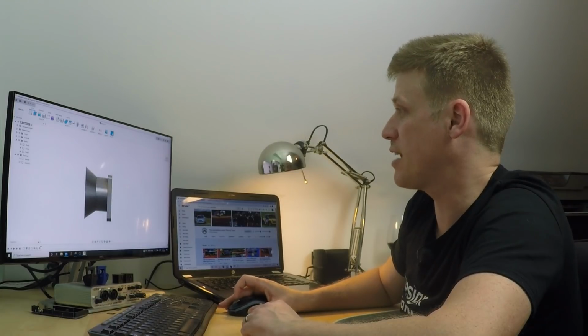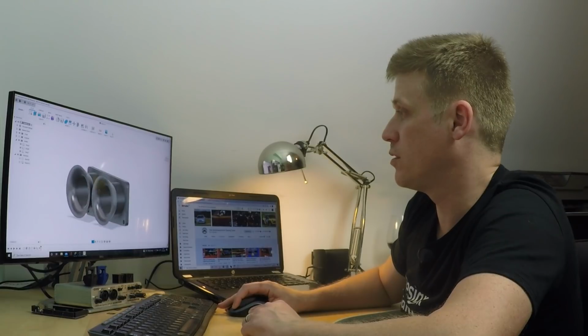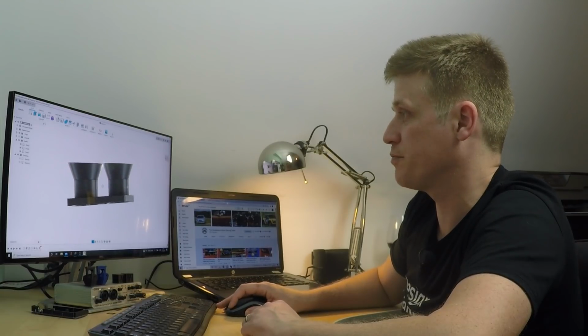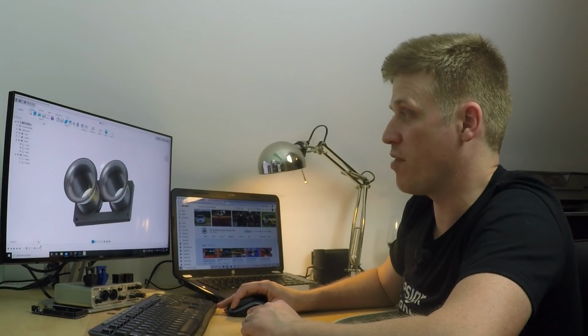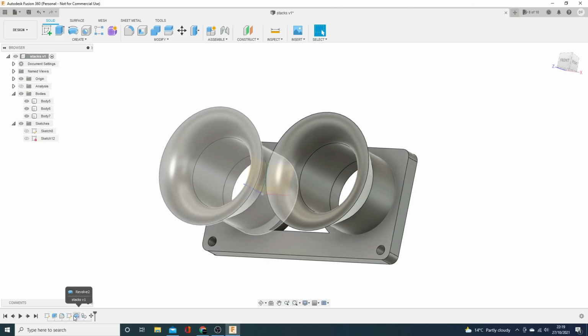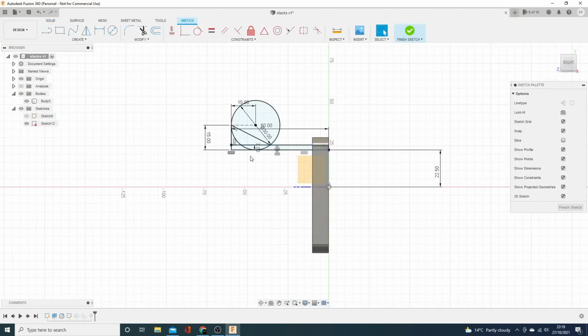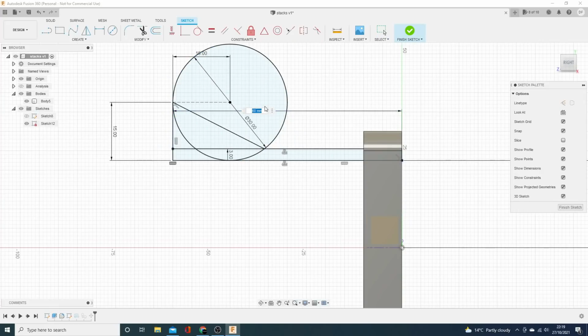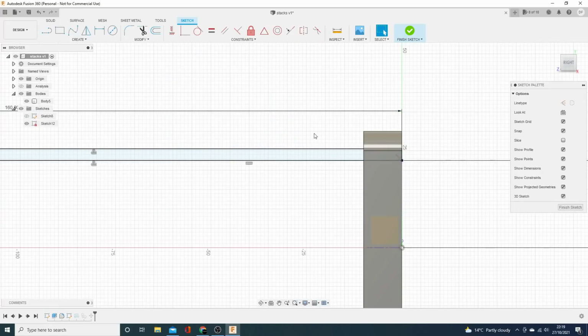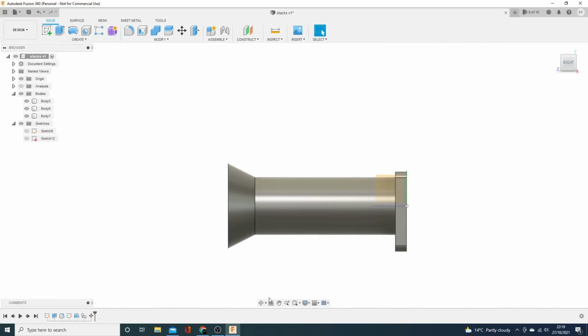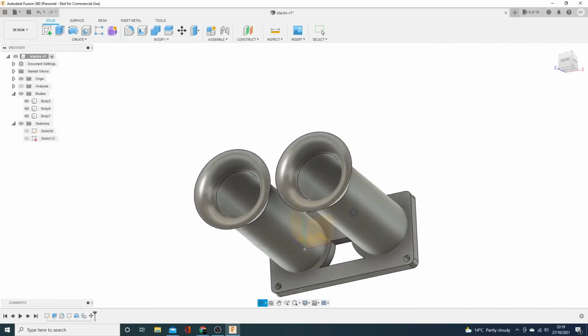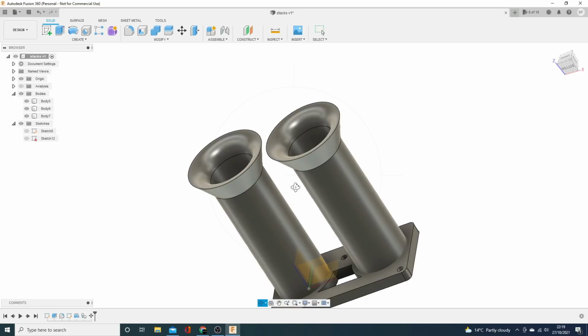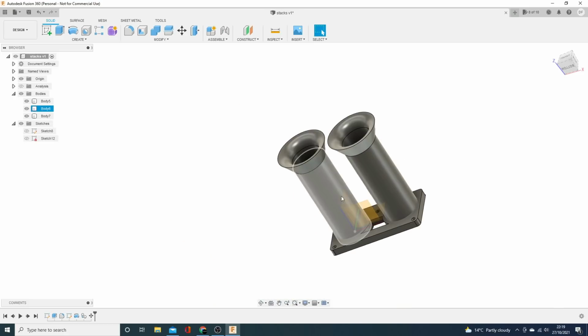And there you have it. So now we've got some 60 mil velocity stacks. If I want that to be 160 mil, well, you just go in, change it one more time. And because we built this side directly from that side, as soon as you change that side, it follows it through and it relives the timeline. So it makes changing things really, really easy.